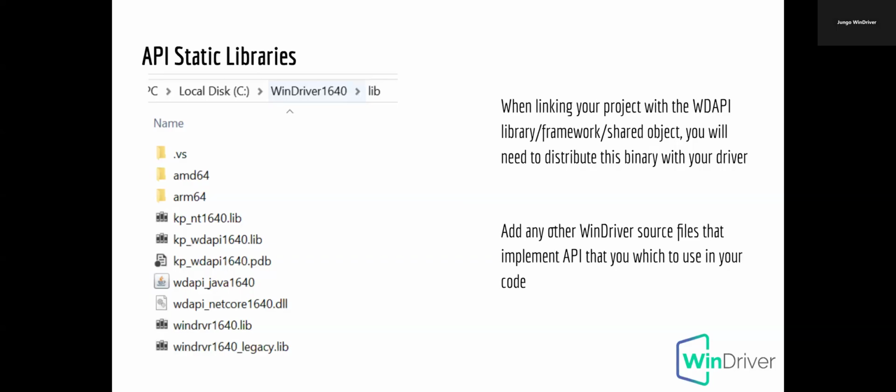So if you generate the project now, you will have everything the driver needs to work, and everything you set up in the driver wizard. If you have components that you've added in the old version, you need to make sure to include them in the newly generated files.